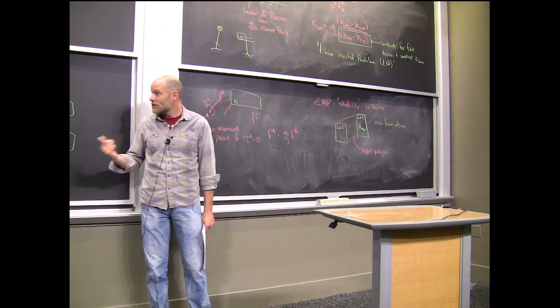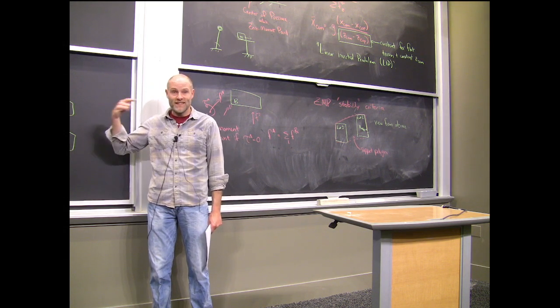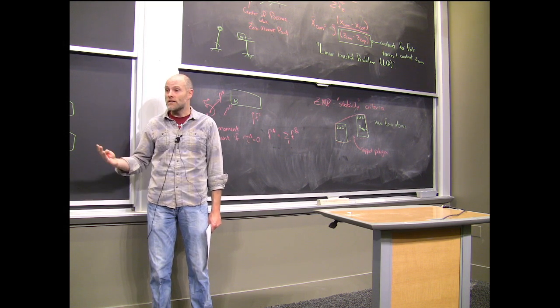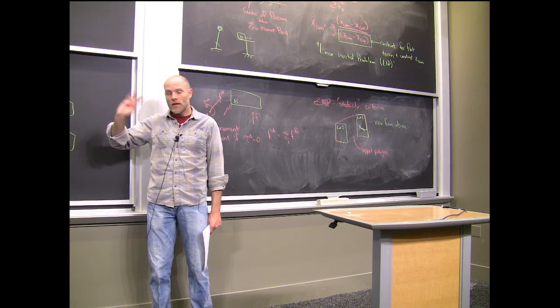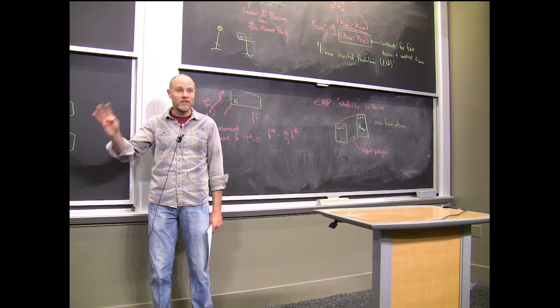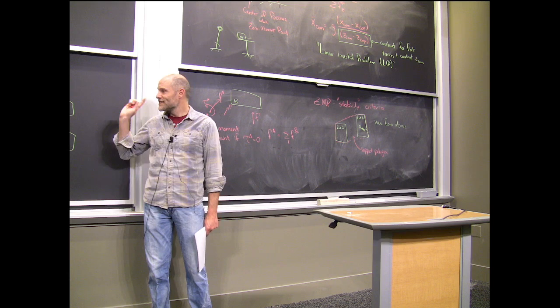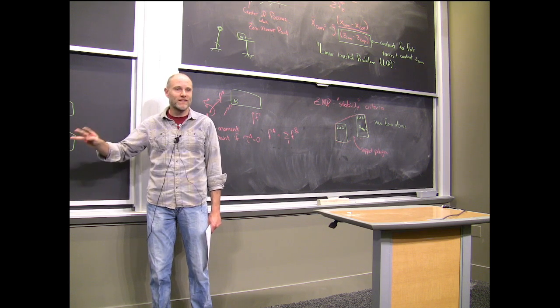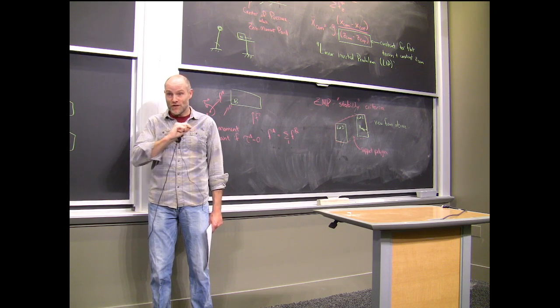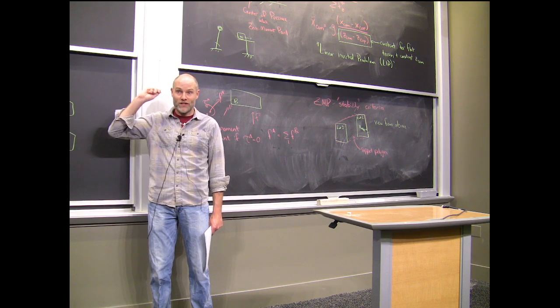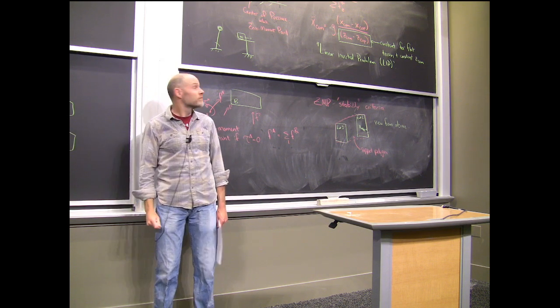All right, so stabilizing your center of mass trajectory is actually LQR. That's crazy, right? We just talked about compass gaits and everything like this. Stabilizing those was much harder. This is not a linearization around some nonlinear system. This is just straight up LQR. The dynamics are actually linear. Time invariant linear.